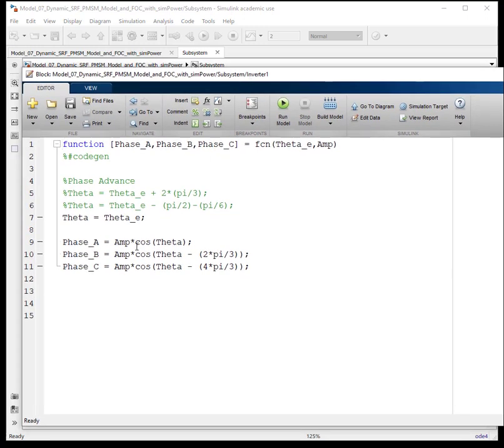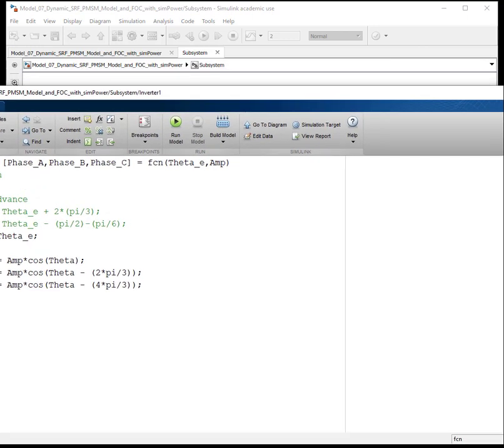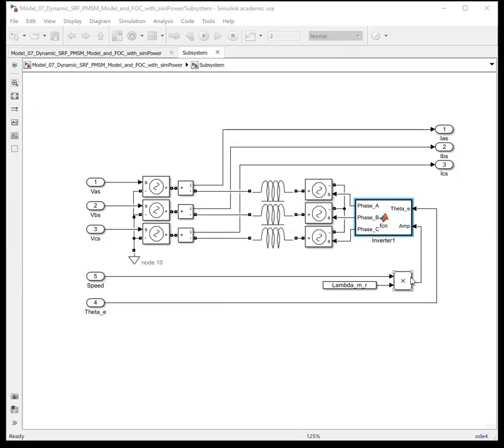Okay, so specifically if you look at the back EMF, it's in the stator reference frame, and it is a function of theta. We are setting the amplitude based on the flux linkage coefficient, lambda m. If you'd like, you could code the lambda and the speed, the product, the amplitude calculation yourself in here. I chose to do it differently. I chose to have it externally calculated and then fed in. It doesn't make a difference.